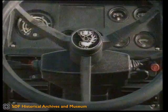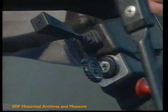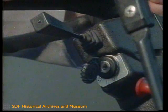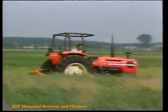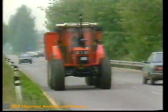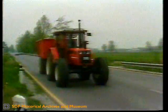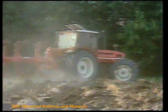Safety in the use of the tractor. Starting the tractor only with gears in neutral. No risk of accidental moving off. Protection of all moving parts and all hot parts. No risk of accidents. Reactive type hydrostatic steering. Accurate, safe steering even at high speed. Hydraulic lift with non-return valve. Prevents accidental drop of implements with engine off.